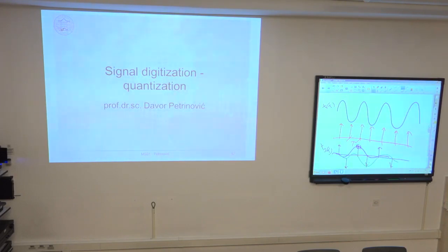First weight, another weight, and so on. While this flash AD converter does it in 1 step. It simply, simultaneously compares the input value to all 128 or 256 levels and finds which of those comparators were below and which are above the threshold. Okay, the code is this.